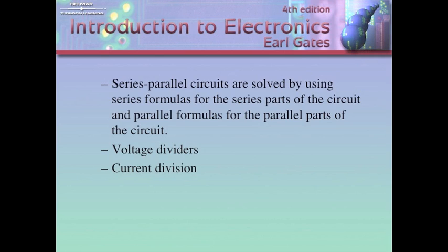If we're going to have 2.05 amps flowing through this resistor, and we've got 500 milliamps flowing through this load, how much current is going to have to be flowing up through this resistor? .05 amps coming up from here. 2.55 amps. Do you all agree with that?